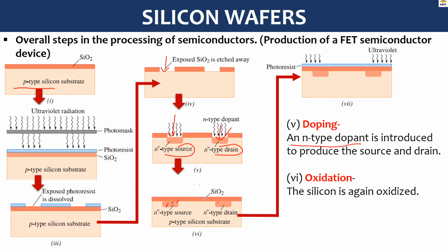And then the next stage, after introducing here your N type of dopant, you now allow oxidation again to occur on the surface here. There's oxidation again, sort of like to cover what's happening inside this wafer. So your oxidation, then you have got your SiO2 layer.